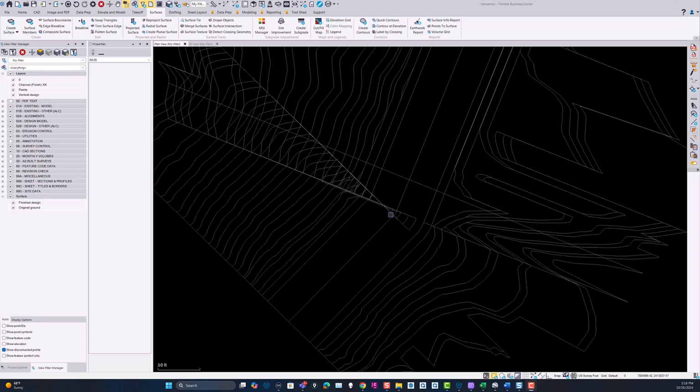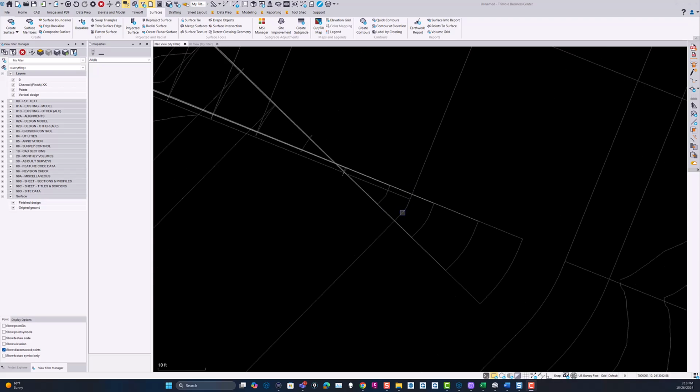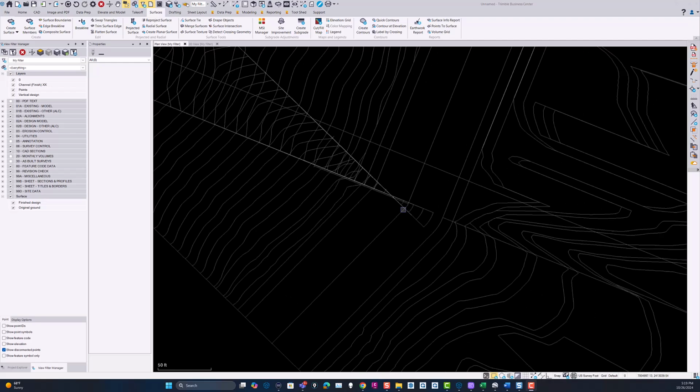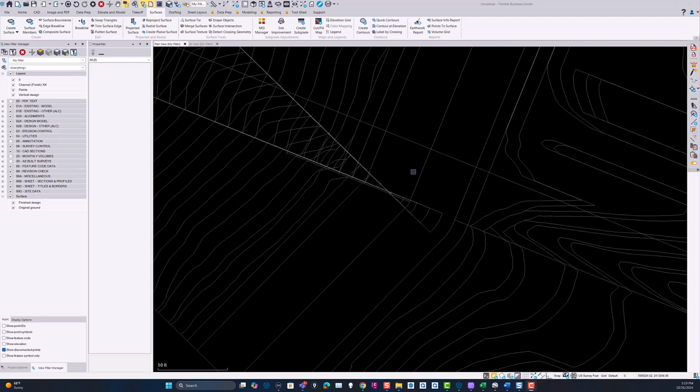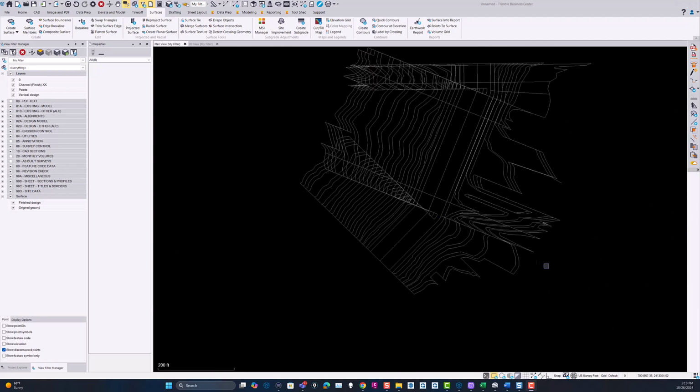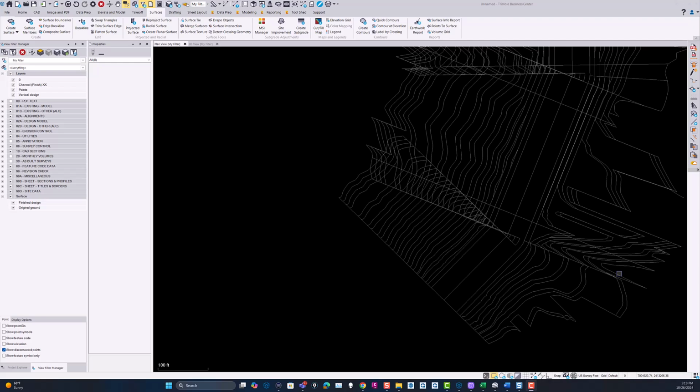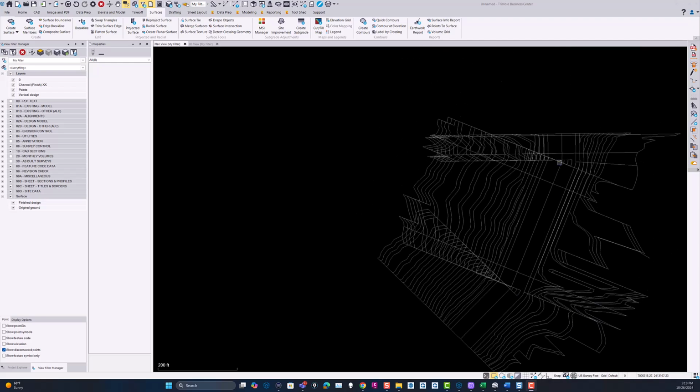And on the outside corner, unless you put a curve into the main line, which I did, you can see there's a small curve here, then on the outside it will calculate around the curve and compensate for the fact there's a gap, because in the same way you project out from here and then you project out from here at that same tangent point, and you end up with this wedge where there's no data calculated in the offset lines, unless you put a curve in here and densify through that curve to make sure that you get enough points to define the benching pattern on the outside of the curve. And the same applies up here.